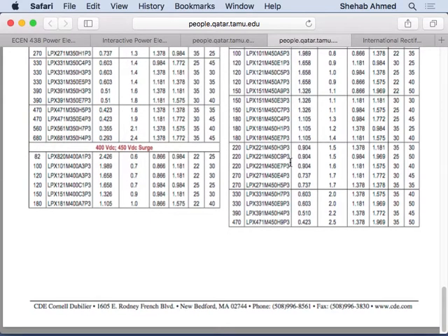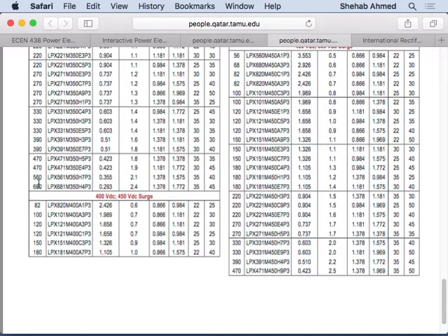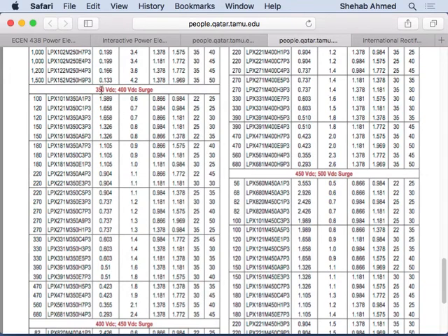The benefit of these things is that they can go to very large capacitance values. You can go to high voltages at large capacitance values. That's the benefit of these electrolytic capacitors. For example, with ceramics you'd never find a 680 microfarad ceramic capacitor at 350 volts.